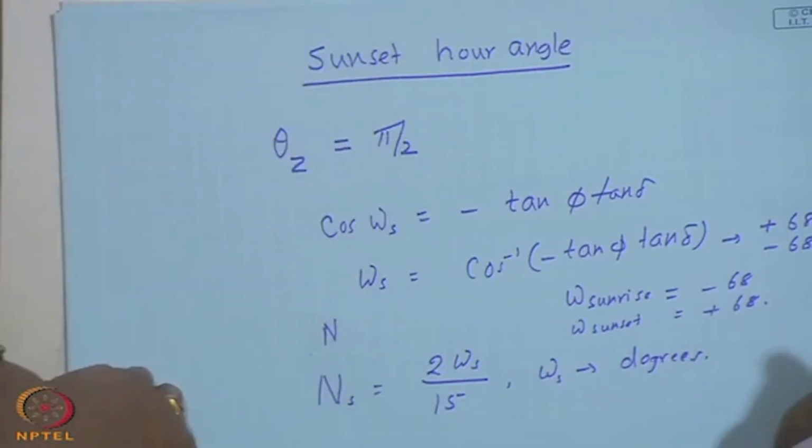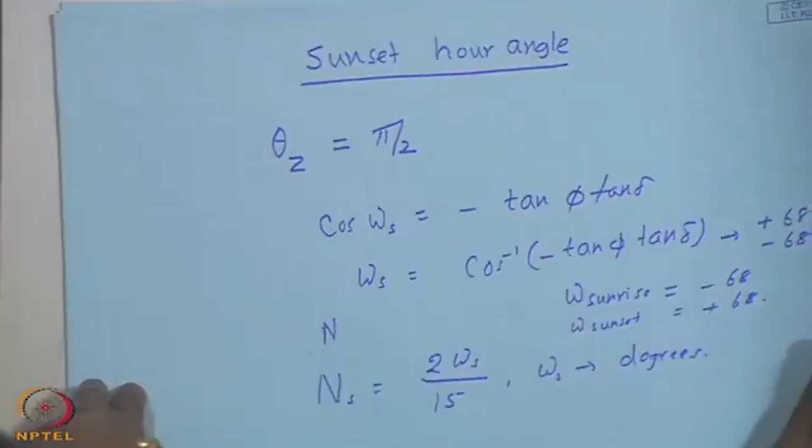You have to be careful whenever we are using trigonometric relations, whether degrees or radians. As a process of integration, if you get an omega, that has to be always in radians, whereas sin 30 or sin pi by 6 is one and the same thing. Whereas, if I multiply by omega s, this omega which resulted from some process of integration or differentiation, I have to use only in radians. That you have to remember.